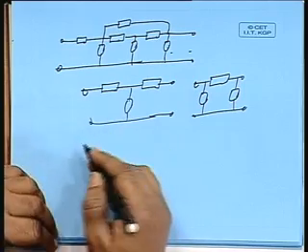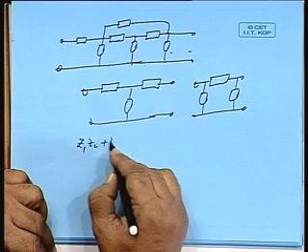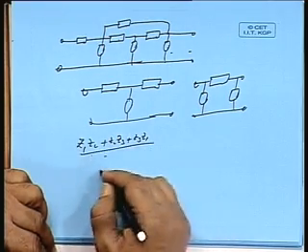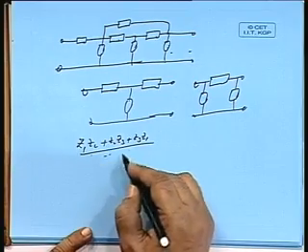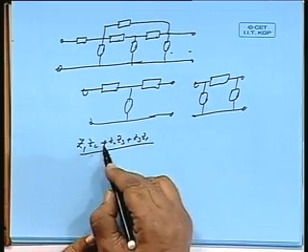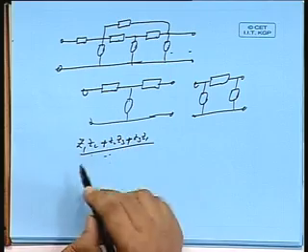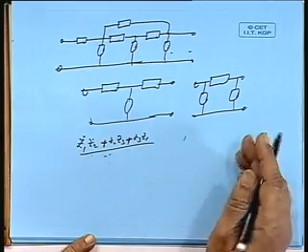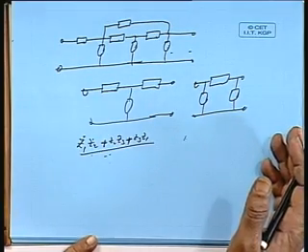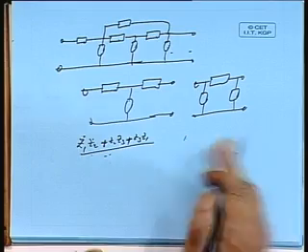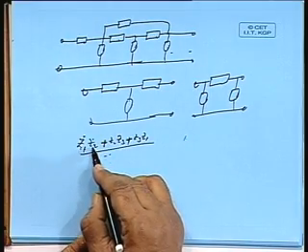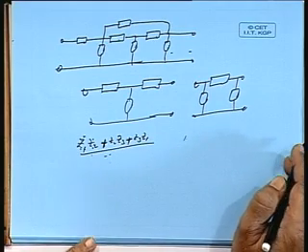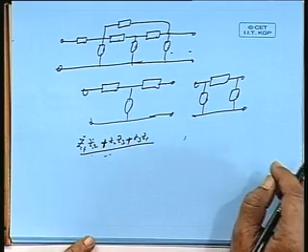Say in terms of impedances, Z1 Z2 plus Z2 Z3 plus Z3 Z1 divided by Z1 or Z2 or Z3. The operations are all positive, there is no subtraction. Now, Z1, Z2, Z3, these will be R plus Ls plus 1 upon Sc or their parallel combinations, series combinations. So, they are all having positive signs, and after multiplication also the signs do not change. Then again you are having additions. So, all the elements will be finally added, there is no chance of a negative sign.